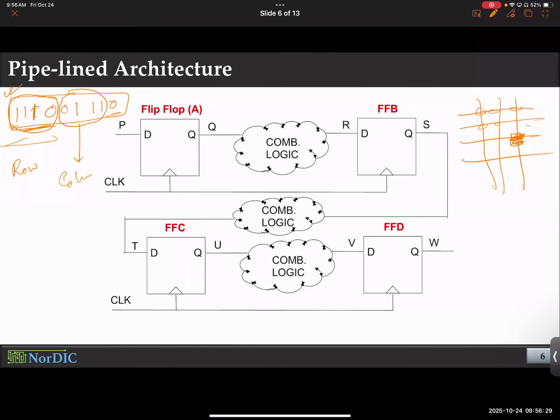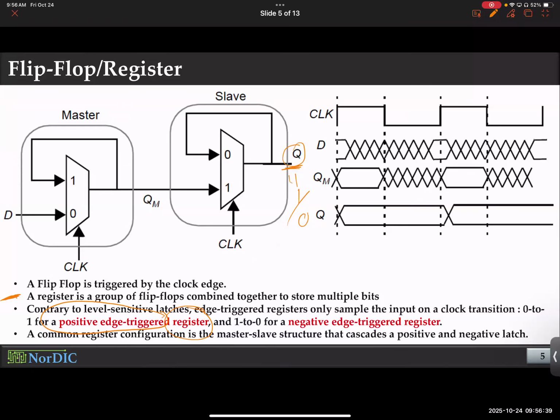But my point is, to be able to do so, you have to keep track of every bit of information, don't you think? How can you count the bits? Did you see in the previous slide that you can basically control every bit, one bit at a time, with one clock edge? So every clock edge will send one bit to the output. One clock edge, one bit. Another clock edge, second bit. Another clock edge, third bit. So you can control it, as long as you control the clock signal.